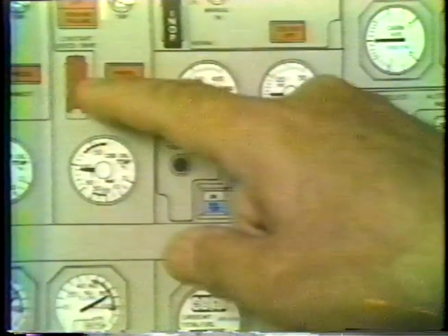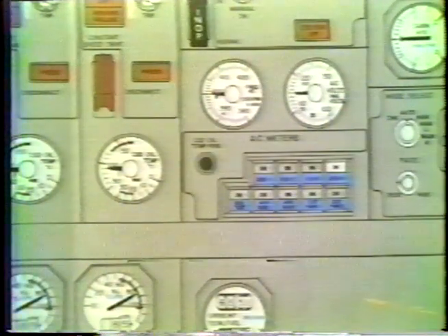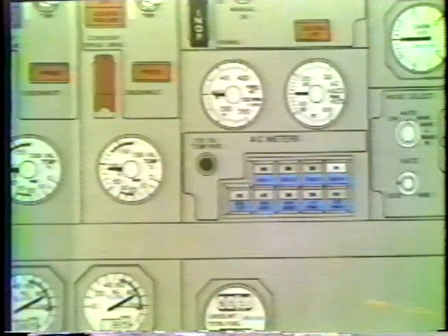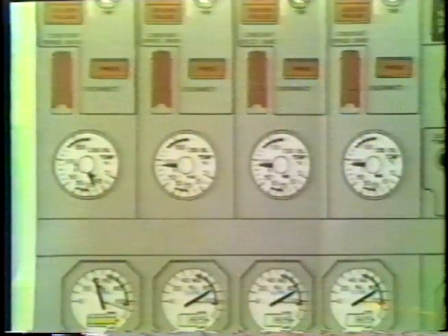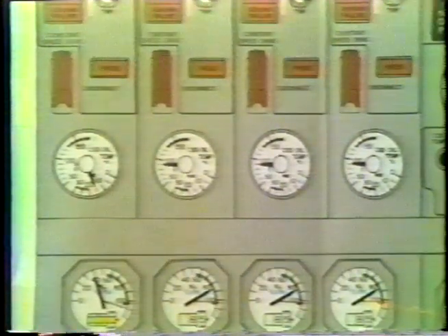If the disconnect switch is operated with the engine not running, the CSD may not disconnect right at that instant, but as soon as the engine starts, it will disconnect. So anytime the safety wire is broken, it should be investigated and made sure the CSD is properly attached prior to engine start.